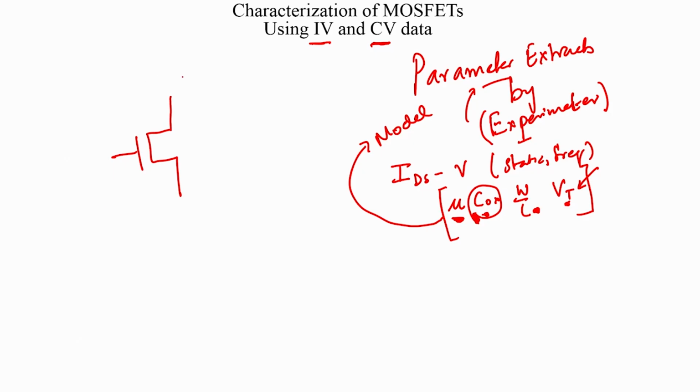So, you have made your MOSFET. Okay. We will just show 3 terminals, we will not worry about the body, and this analysis is true for any other kind of FET structure. We have not talked about, for example, thin film transistors yet, we will cover that, but these ideas are valid for any other TFT structure, and any of the MOSFETs as well. The key experiments to perform, the very first set, would be your IV and CV measurements. So, you have your MOSFET, you have a drain, source and gate.